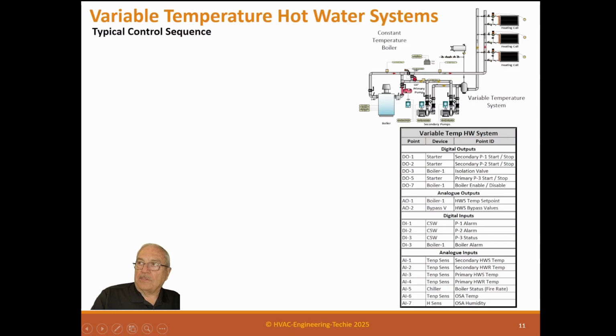So now there is another item here. This is to change the temperature. So if this is running, say, 140 degrees, and we need 100 degrees, then it will begin to mix this water right here like this. And as this heats up, it lowers this temperature, and it only takes what it needs when it's bypassing in that direction. So this is a hot water bypass, cold water bypass, and it allows us to control the temperature.